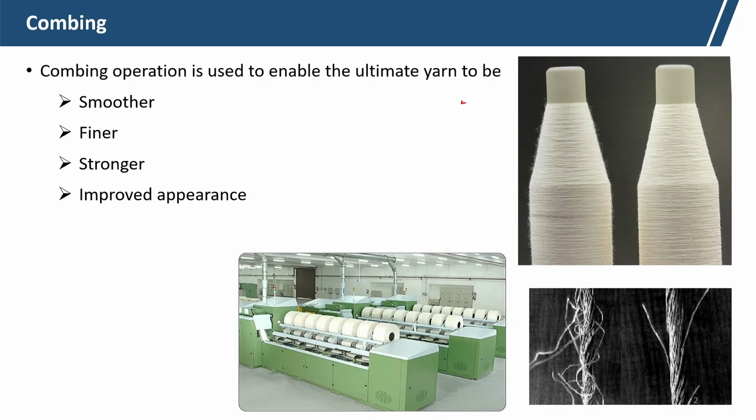So, the yarn becomes much cleaner and more uniform, because the fiber length distribution becomes better, since short fibers result in more and more floating fibers, and the yarn uniformity improves after combing.